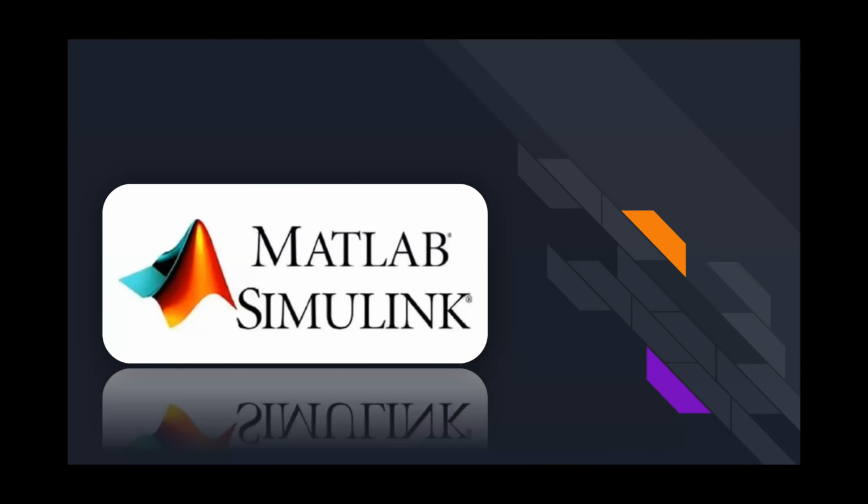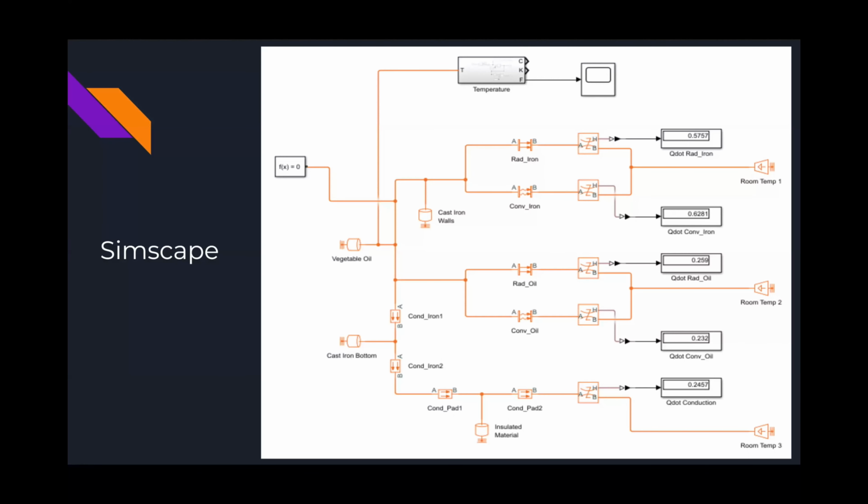The first model we will talk about is our Simscape. In this model, we have 3 thermal masses: the vegetable oil, the bottom of the cast iron pan, and the walls of the cast iron pan. We did not include the handle of the pan in the simulation, as there should be a negligible amount of heat loss to conduction into the handle.